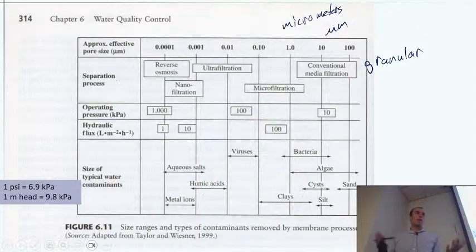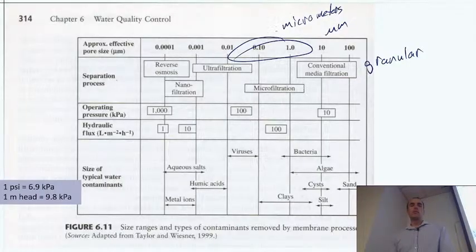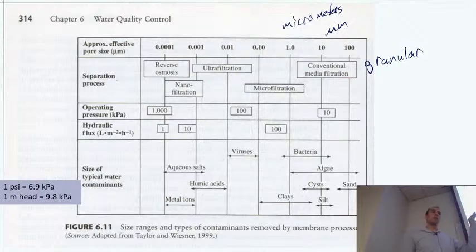So if we take a membrane and apply it with what we call microfiltration, really that's referring to what pore size do we have on the membrane? What size are the average holes? Now, again, if we have one big hole and a lot of small holes, you're going to let everything through, right? So it has to be not just the average pore size, but really the largest pore size of this membrane that's allowing water through it. So if that's in some range to exclude bacteria, of course, then we're removing bacteria.